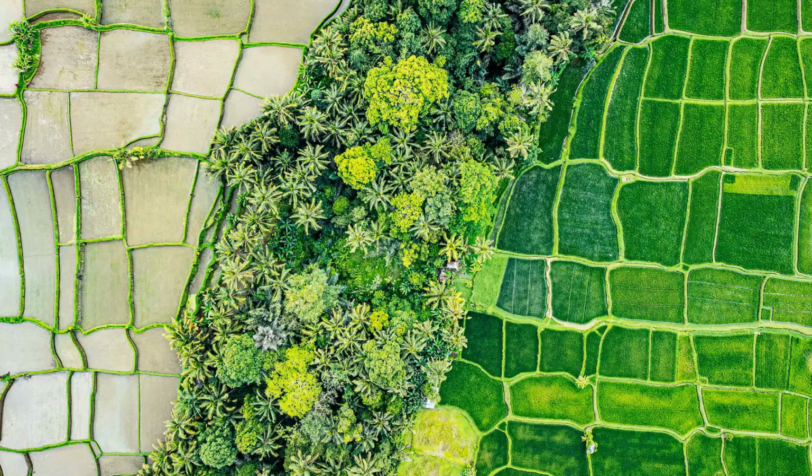And for the mobilization of strength of the support system that I already mentioned, we can plot the tunnel support capacity plots, and we can see the actual force mobilization over rock bolts, whether it is exceeding the strength of the rock bolt or not, so that we can analyze directly from here.